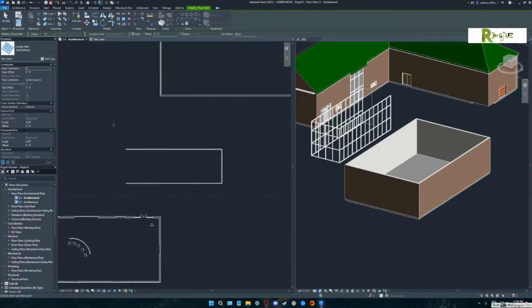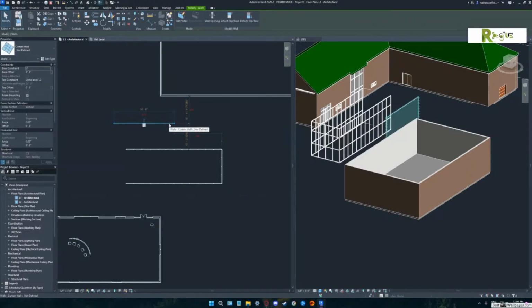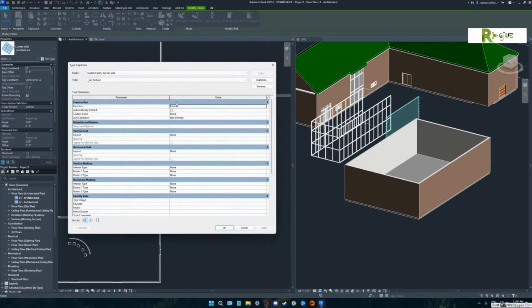Yeah. I apologize. We'll get this stuff ironed out and it'll start working a lot smoother. So just go ahead and draw me a piece of wall. I want to see what this not defined guy that they created is. That's what I thought it was going to be. Perfect. And then hit escape 2 times. Now pick that wall and say edit type. That's what I wanted to see. So they've got nones in all of the stuff.